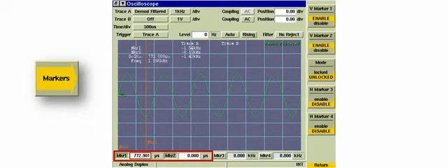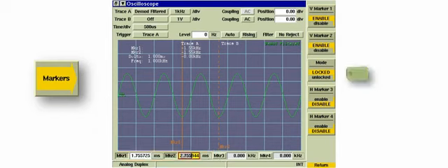We will now position Marker 2 to calculate the frequency of our audio signal using the delta function above the signal and highlighted in red. The mode soft key defines the lock-unlock state of marker 1 and marker 2. The lock state links marker 1 and marker 2 together at the current frequency spacing. When the markers are locked, moving marker 1 or marker 2 moves both markers while maintaining the current frequency spacing. Selecting unlocked removes the link between the markers.